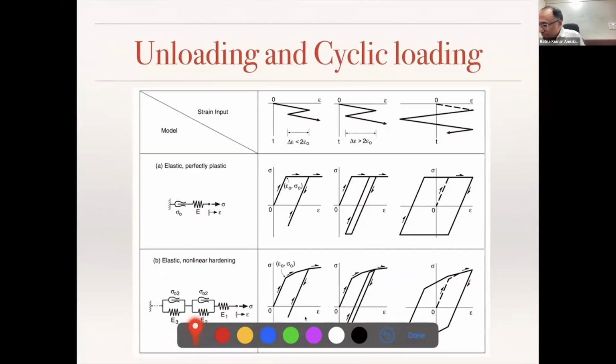It is exactly like what you would see in stress. Let us say this is time, that is strain. You have increased strain up to some value, and normally if you reduce and do the cycling like that, this is repeated loading. But in this case, instead of completely cycling, it went up to this value and then unloaded only up to this point and then reloaded again.